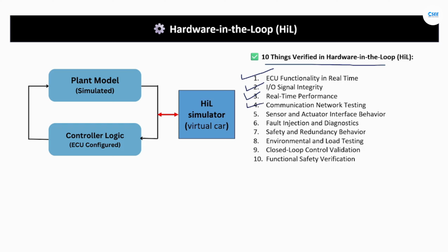Communication network testing, validating CAN, LIN, FlexRay, and Ethernet message timing, IDs, and data consistency. Sensor and actuator interface behavior, ensuring signals match expected levels, scaling, and fault responses. Fault injection and diagnostics, simulating open circuits, short circuits, signal dropouts, and checking diagnostic trouble codes. Safety and redundancy behavior, verifying fail-safe transitions, watchdog recovery, and safe state entry.